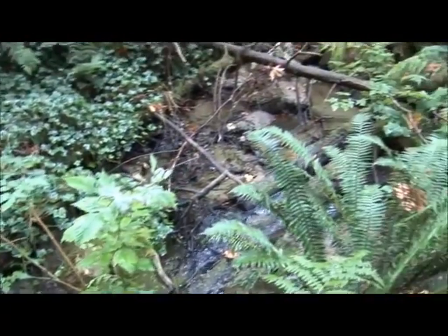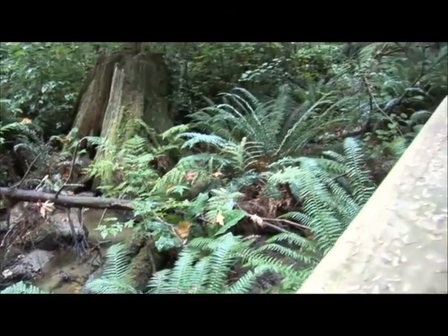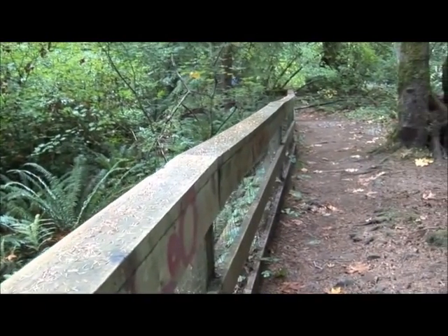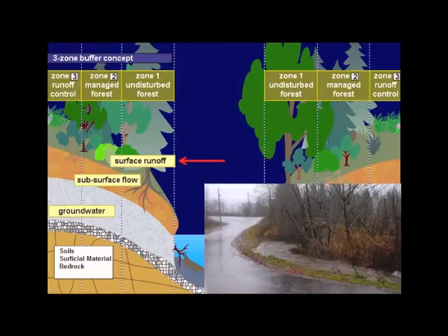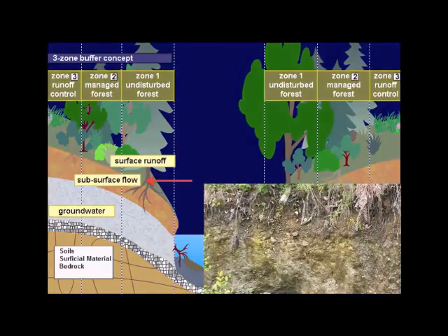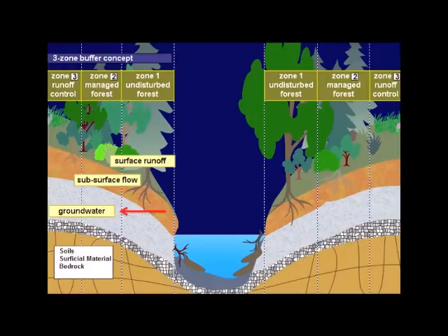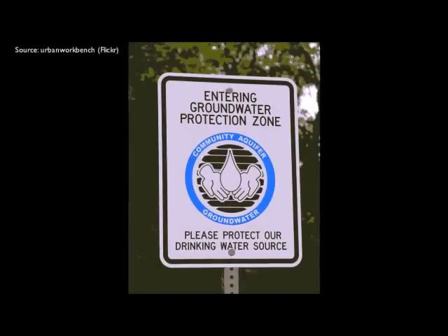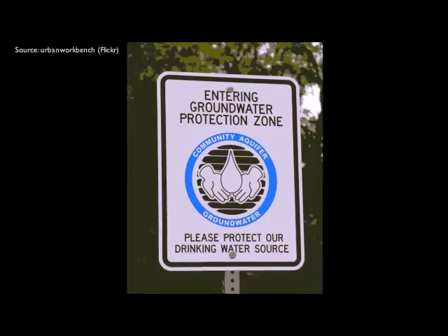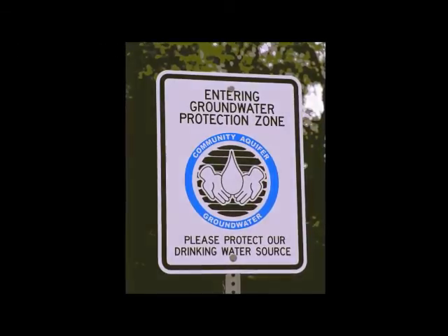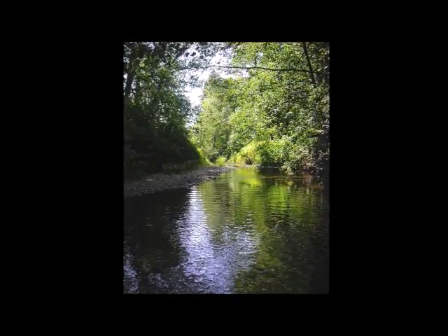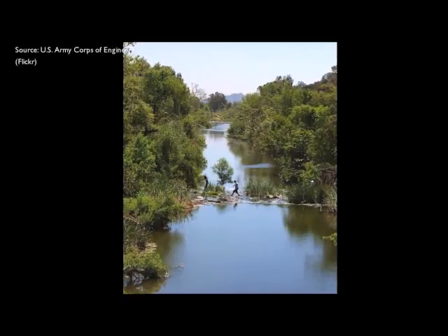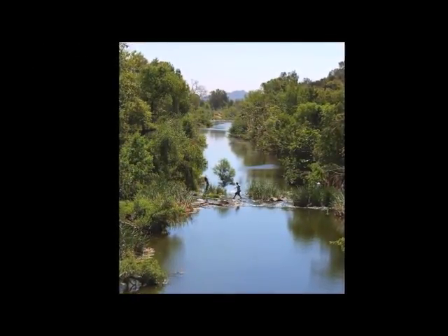Using park space, like William Griffin Park around Mosquito Creek in North Vancouver, is one way to allow for wider buffers. Good riparian buffers can be thought of as a continuous three-zone concept that addresses surface water, soil water seepage, and groundwater inflow. Also consider that watershed boundaries do not typically take groundwater into account. Allowing runoff to be detained within the buffer zone, facilitating infiltration, and having a well-developed and vegetated buffer can greatly reduce the impact of stormwater runoff.